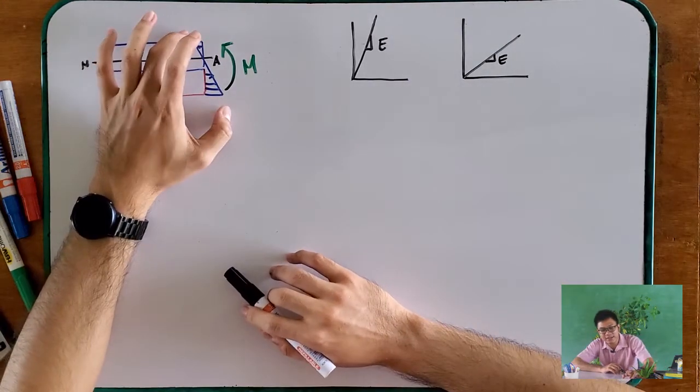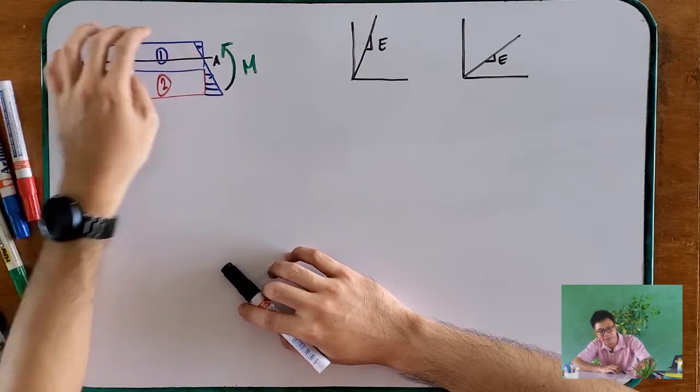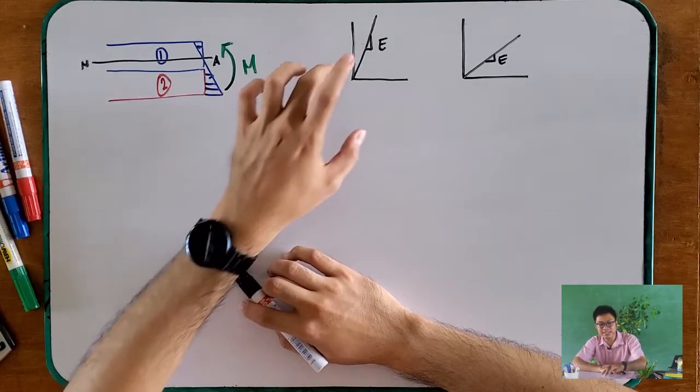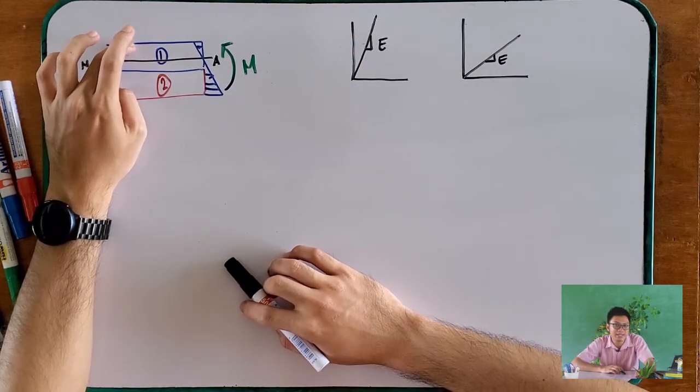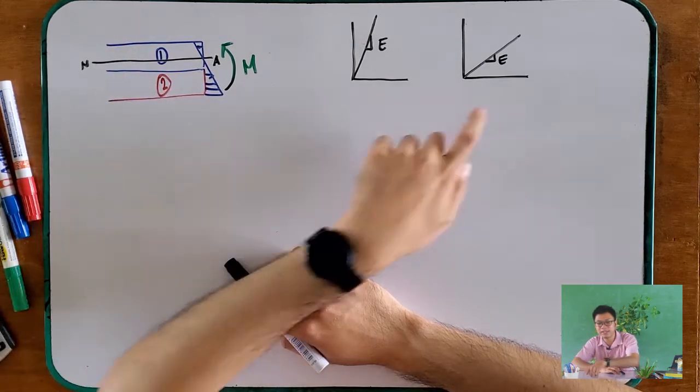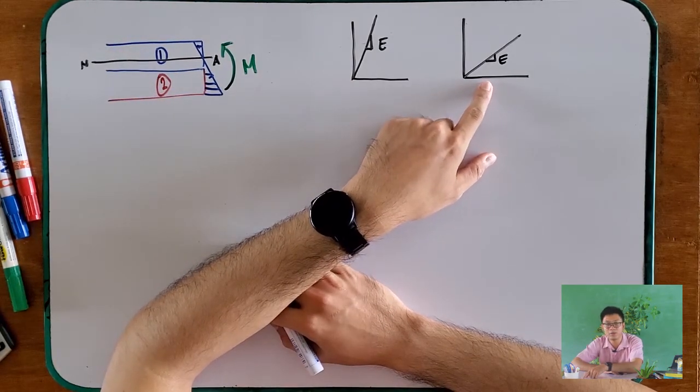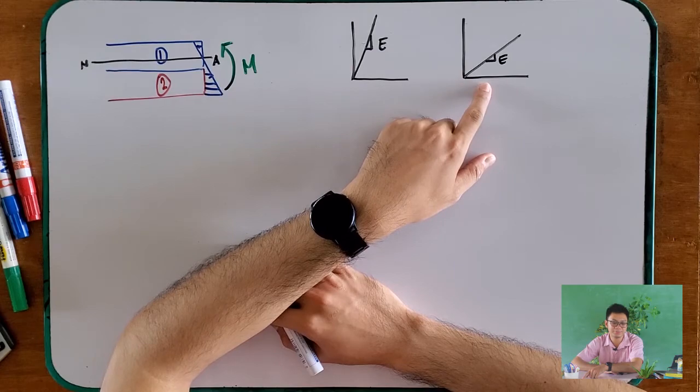Their behavior in strain, take note, the word strain, is a linear relationship, for 1 and 2, the compression or stretching of the material is linear. But in stress, they behave differently. The stiffer material has larger stress compared to the material with a small modulus of elasticity.